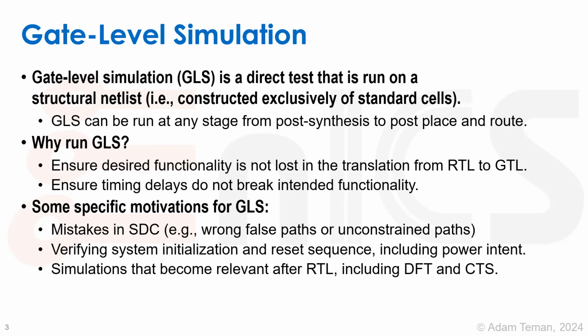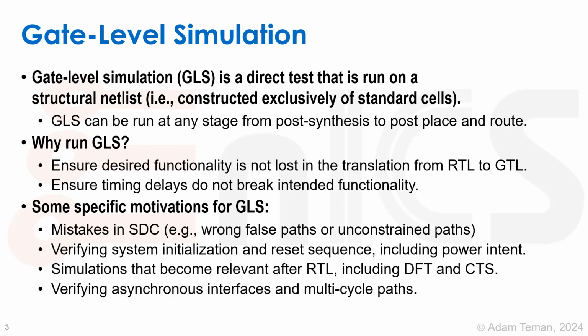So different things come in after doing a whole place and route flow that are different than what we had in our RTL, and we want to see that we didn't break anything. There are things like asynchronous interfaces and multi-cycle paths, which aren't exactly checked by SDC. Maybe if we build the SDC in a certain way, we check it to some point, but this will actually be able to simulate these things with actual timing. And the last thing which we're going to show today is capturing switching activity for power estimation.